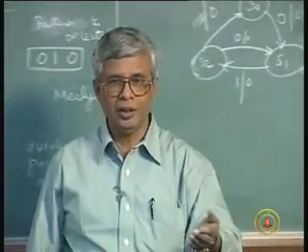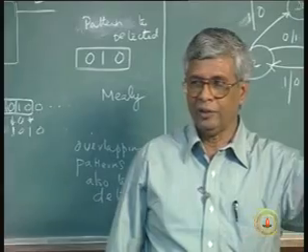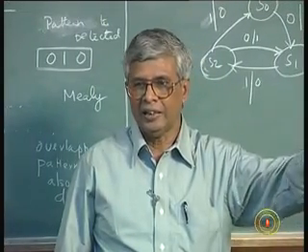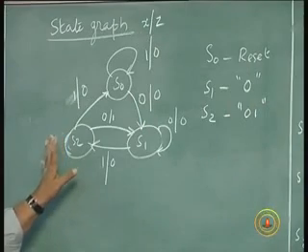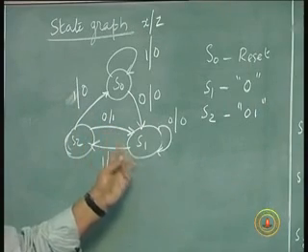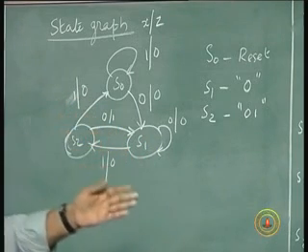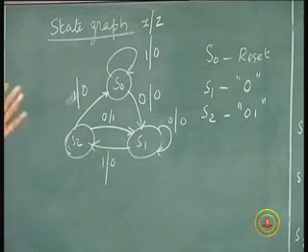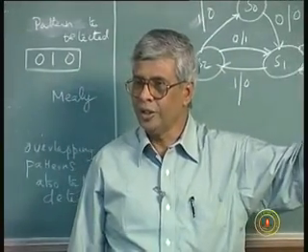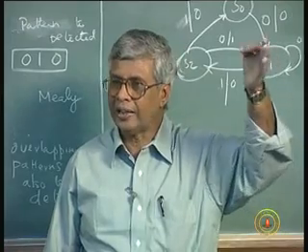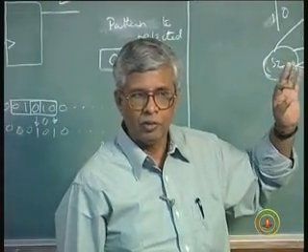So the idea is that from somebody's description of the problem to the final realization of the circuit, you have to go through all the stages, and this is the most critical stage, because understanding the problem and translating it into a graph. From here on it is a routine procedure, from state graph to state table, state table to transition table to Karnaugh map to gates, gates to buying them and then putting them in the breadboard and testing it. It's all routine. No? The most critical part of this design is to understand the specs and translate it into a workable state graph.